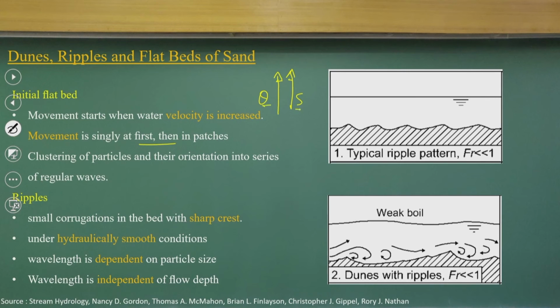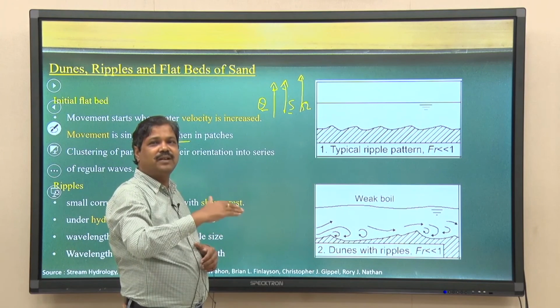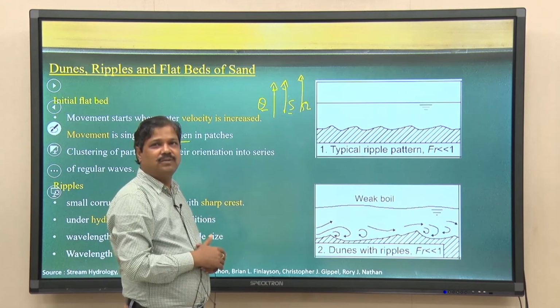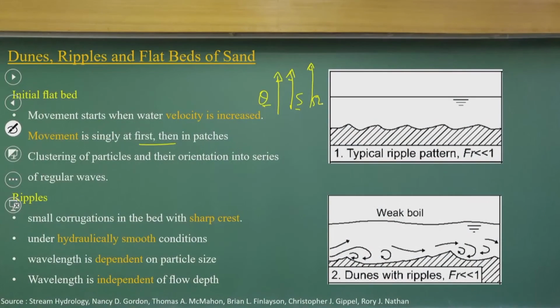Where the slope is changing and Q is changing, we are increasing the stream power. As the stream power increases, bed material starts moving. Because the bed material moves, the particles form different bed shapes. So that is what we look at as the stream power increases in a flume, and you can also see these river bed forms in the field.